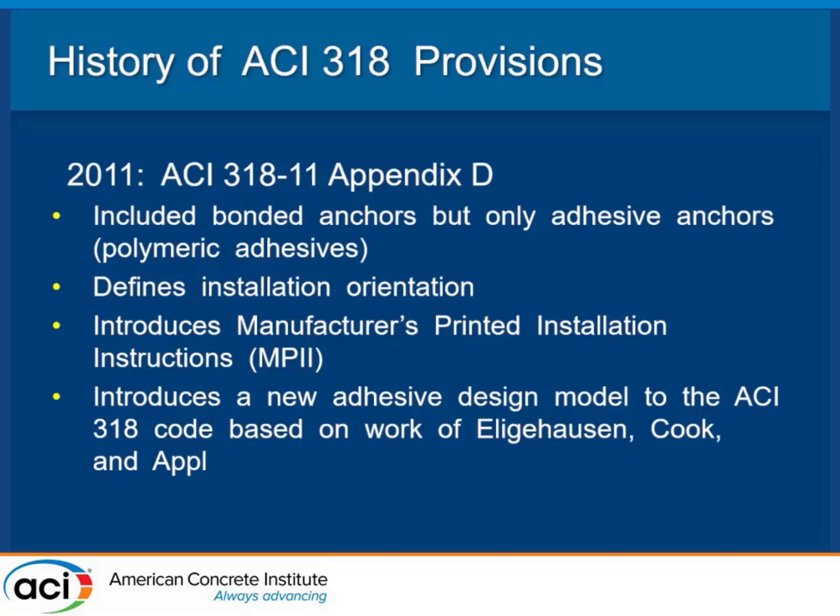Basically it says, if you're installing an adhesive anchor horizontally, inclined, or up above, we also require that the installer be certified. And we actually have requirements for inspectors to be certified. Why? Largely because of the Boston Big Dig, and doubly why? Because when you install an adhesive anchor, there are over 20 different mistakes you can make in the installation of that anchor, which will affect the strength of its installation. 20. I don't know if you can name me one just sitting there. So it's a much bigger problem than people think it is.